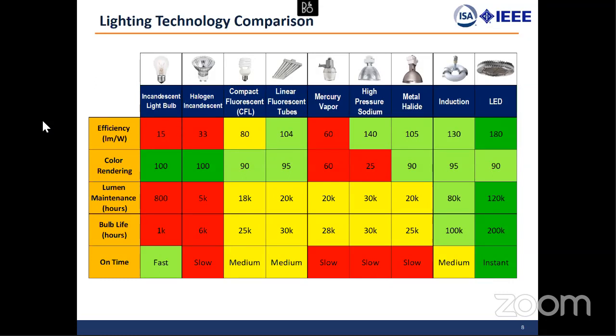Hey, Glenn, let me just add that was a big problem when LED white lighting first came on the scene for the engineering community, especially. You were putting lumen for lumen back up, and everybody's like, "Oh my God, it's way too bright." And that's a function of the biology of the eye. Your eye perceives certain parts of the spectrum distribution curve a lot better. UV on the LED side, high pressure sodium is on the warm side, and infrared side. It's more than just the intensity of the light. It's the human condition that lends itself to perceiving this type of light much better.